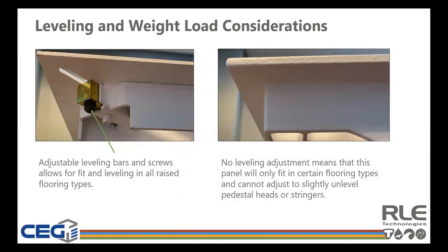The panel on the left will fit into just about any flooring system because it's equipped with adjustable leveling bars and set screws, whereas the panel on the right will only fit into a specific manufacturer's flooring systems. The panel on the left can also be adjusted to match the level of the existing floor, even if there are small differences between the four pedestal heads supporting the panel. In that same scenario, the panel on the right will end up rocking or wobbling, which again potentially degrades its weight rating.